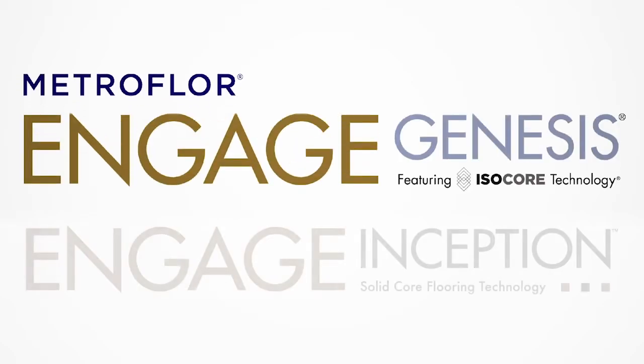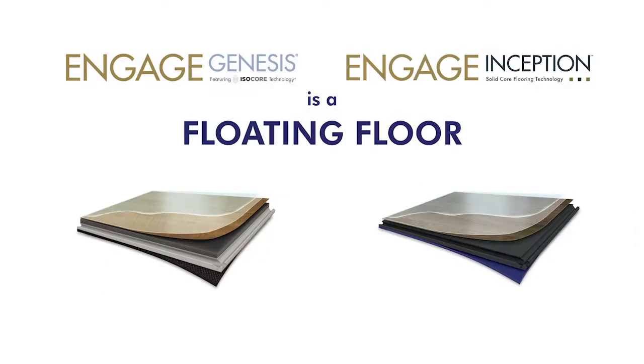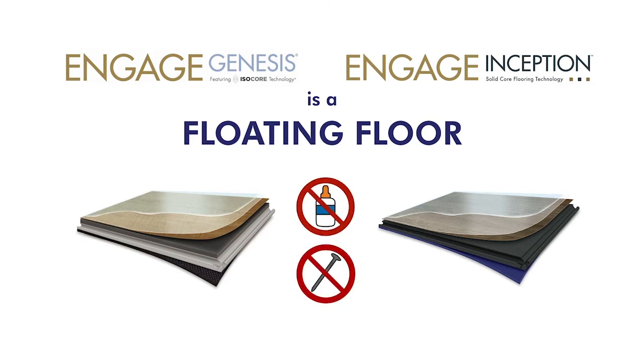In this video, we will demonstrate the Drop Block 100 procedures of Engage Genesis and Engage Inception LVT. Among their many advantages, Engage Genesis and Engage Inception offer fast, easy installation, even over subfloors with minor imperfections. Genesis and Inception are designed to be floating floors and must be allowed to expand and contract freely. They should never be glued, nailed, or fastened to the substrate in any way.